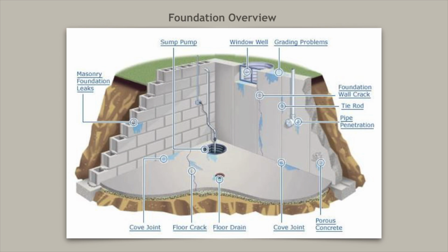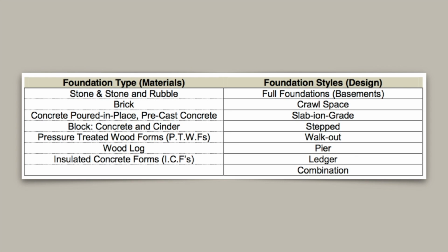Footings are located underneath of the foundation wall, which sits directly on what should be undisturbed soil. The footings carry both the dead load, the static load, and live loads, dynamic, of the house and transfer these loads onto the ground below. During this lesson, you will describe foundations in two ways: types and styles. Review the chart on this screen for the types and various styles of foundations.